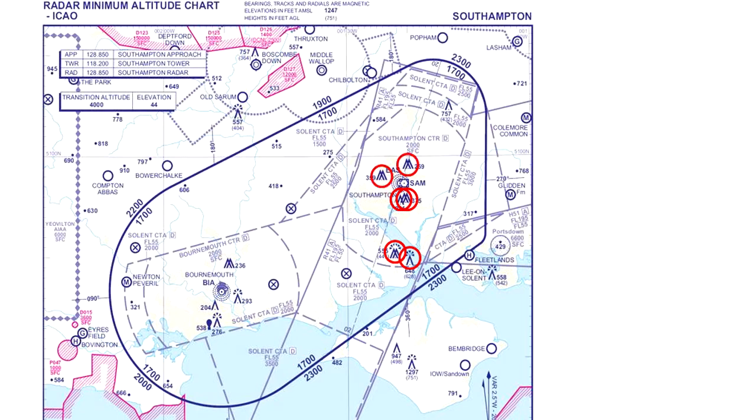This area will have been surveyed for obstacles, and minimum altitudes will be specified for each sector of the area. Minimum altitudes will be high enough to minimize the activation of aircraft ground proximity warning indicators. But should such systems be activated, then states must encourage the operators to report them. This will help prevent reoccurrences.